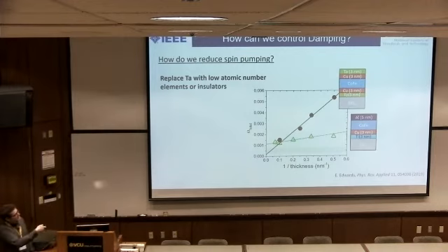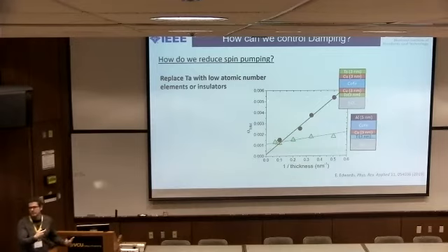But the problem is in a device, you're gonna have a complicated structure. And so take, for example, here where we use a copper tantalum seed layer. It's nice that the intrinsic is so low, but ultimately if you have a 2 nanometer film, the total damping is actually 0.005, an order of magnitude larger. And that's really what matters.